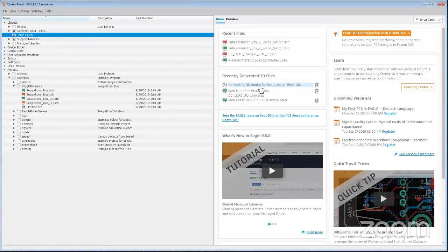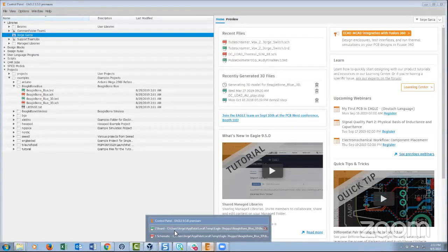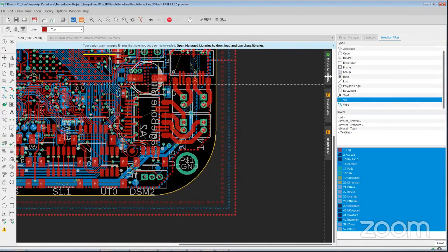Any workarounds for when trying to render PCBs in Fusion 360? The green solder mask does not render properly. A green mask with yellow tint does not seem right. Is there a way to change the solder mask color? Yeah, sure there is. We've had that for a while. You just go to the manufacturing flyout menu and you can do it from there. Sure. Yeah, we've had that for a while, Isaac.